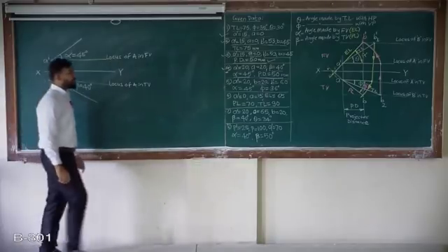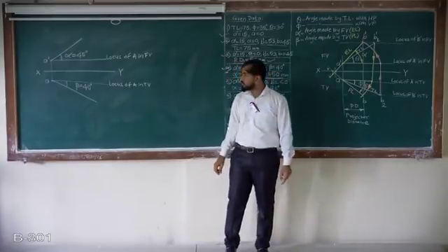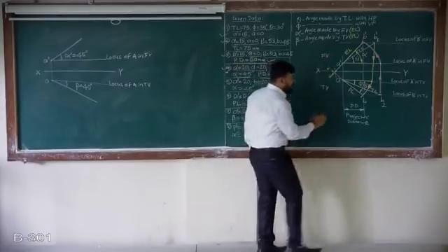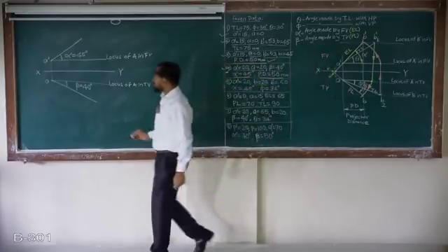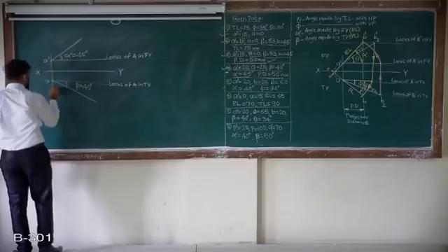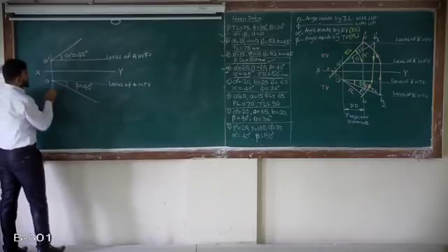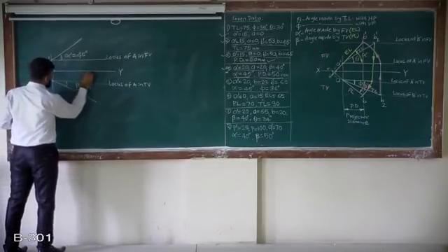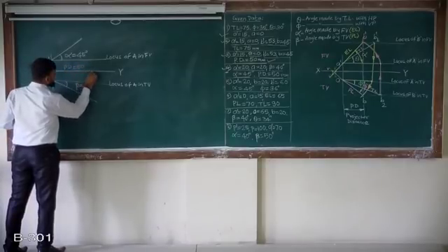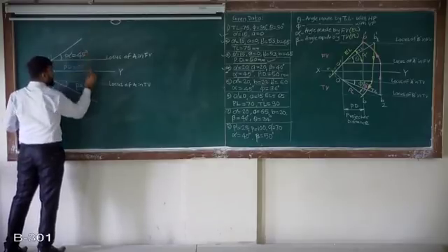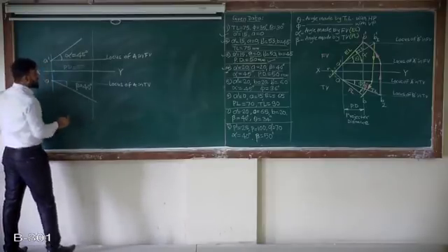Last, very important. Now I was knowing A dash A, I plotted, I know the apparent angles alpha in front view, beta in top view. The projector distance is given. So same again like the previous problem, I know the projector of B and projector of A. So same, parallel to the projector of A or perpendicular to XY, I will draw one projector line at a distance of 50. So let's say from this XY, I will mark the projector distance as 50 mm. Let us say this is the point, and from this point I will draw one projector. So this is the projector of point B.